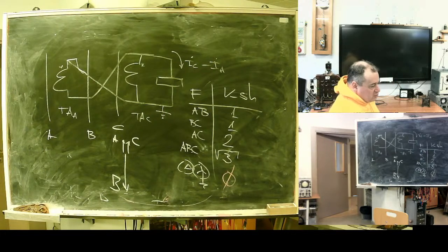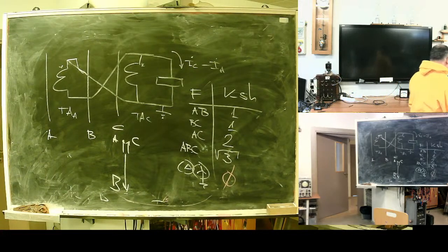At the moment you're building a trade mall, you need dry transformers because of safety regulation. Okay, you can go with a fire resistant wall. But if you put new transformers, delta star, instead of old star, not grounded, star grounded, you're in trouble because your protection will fail.